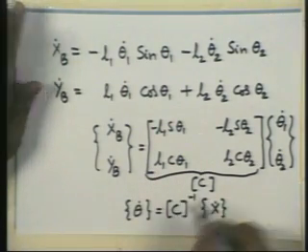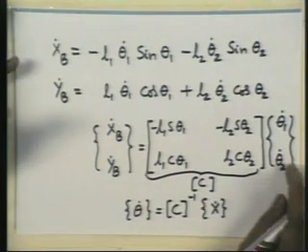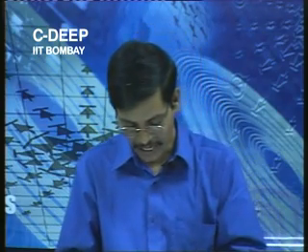Now, whenever you are thinking in terms of an inverse of a matrix, it is conceivable that the inverse may not exist. So, you could get into trouble. All that it means is that the data that has been given in terms of the end effector's desired velocity at that position is not achievable, because the particular configuration of the mechanism may be in a singular configuration.